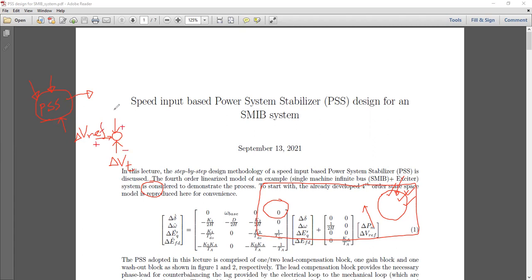And the third input was actually the UPSS, simply UPSS or del UPSS, whatever you say. You can erase the U part. So simply it has to be understood that UPSS is a linearized version of the output from the PSS block, power system stabilizer block. So we'll be talking about the generation of this signal today.